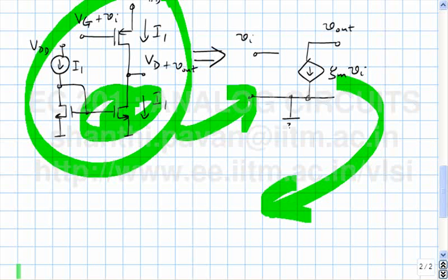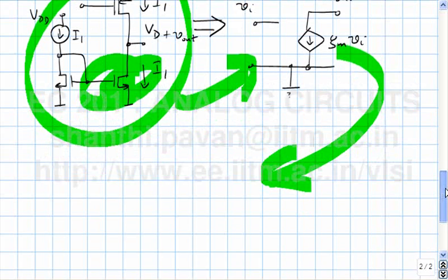The cheapest thing you can do, you don't have to think at all. You just look at the circuit diagram, you'll be able to tell me. You can change the NMOS and PMOS. Have an NMOS transistor in the gain device. The load can be a PMOS current mirror, and you change the appropriate directions of current and all this other stuff. So let me show you another alternative.